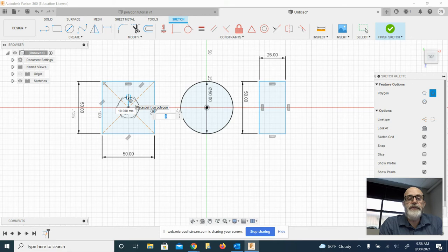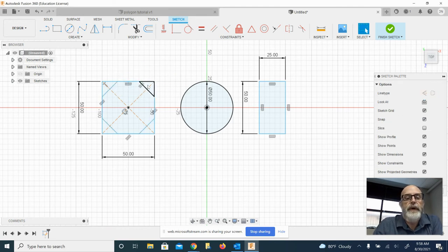And then the other boxes, we're going to set the number of sides. Let's change our number of sides to 8. Was that an octagon? I believe that is. And then let's drag straight up, and let's snap it to the edge of our rectangle. And click Enter. So, escape to get out of the tool. Our polygon is shaped right there. And notice how it's sharing the edges with the rectangle on each side of the rectangle. Okay?